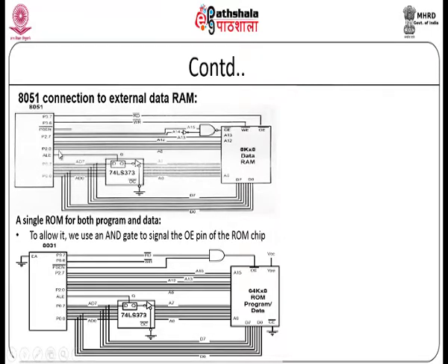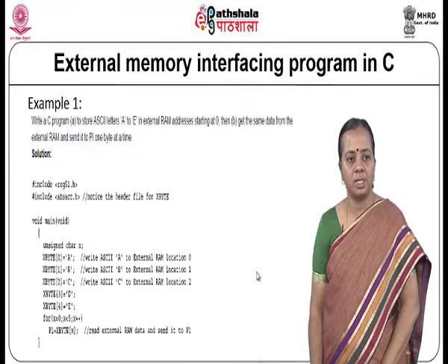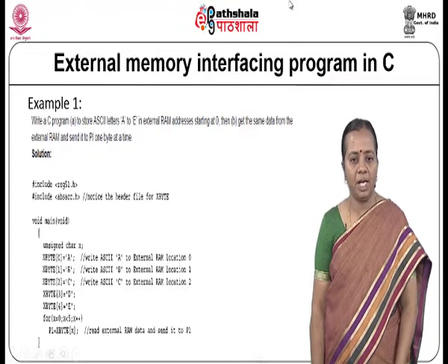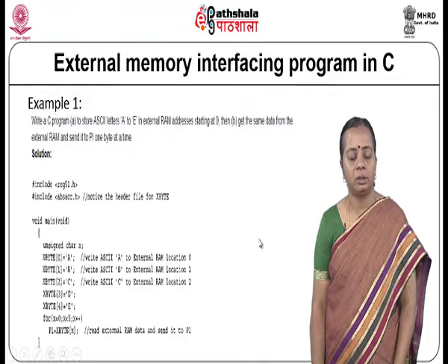If I am looking at an external data RAM connected through this kind of setup, P0 is connected over there, and P2 is connected over there. These two are address lines, and the data line is connected to P0. The read and write bar are connected to OE and WE for selection as well as writing. And if it is a program, then PSEN is connected to OE bar, so that chip selection is enabled. So, this is an example for reading data from your external devices.